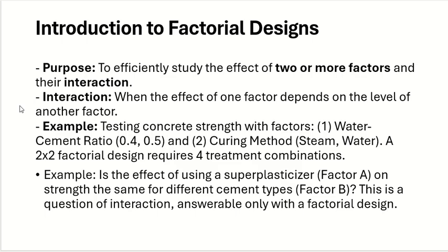So if I'm using a curing method, for example chemical curing, and I give you a value after 3 days, will I get the same value after 28 days? No. So this is what? The interactive effect. I can only get this much strength with chemical curing if the curing is done for 3 days. Got my point? This is called the interactive effect, where the effect of one variable depends upon the other, or the value you are getting is conditional upon a specific value of both variables. If you change any of the values, the output will change.